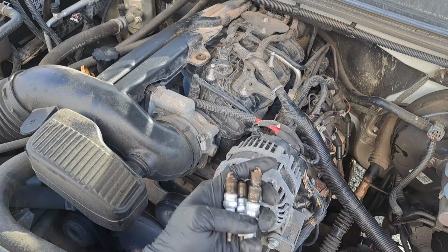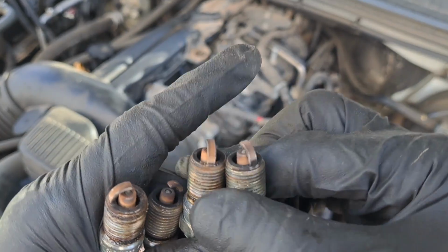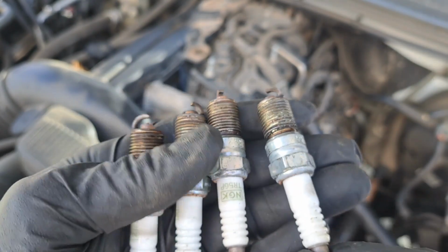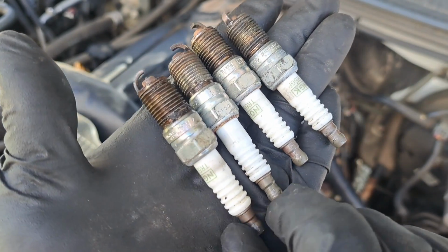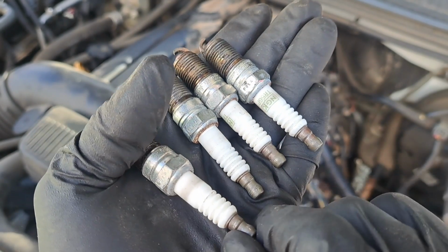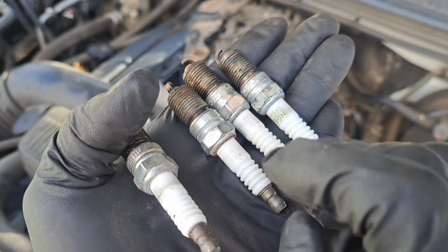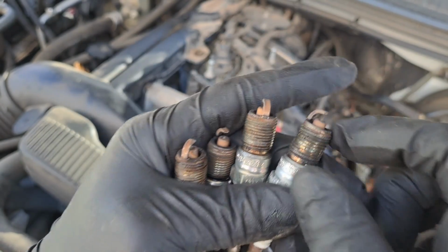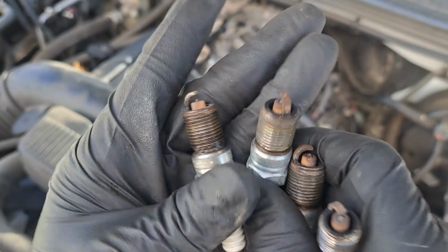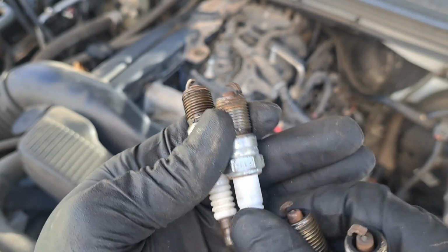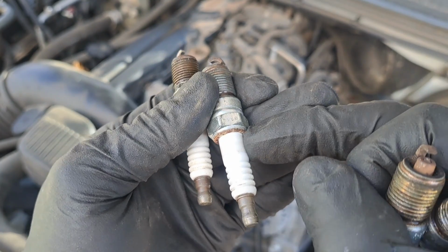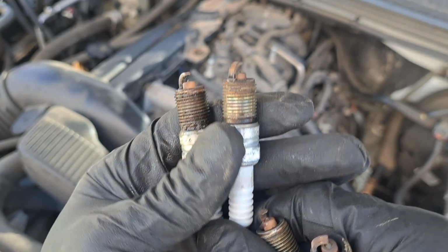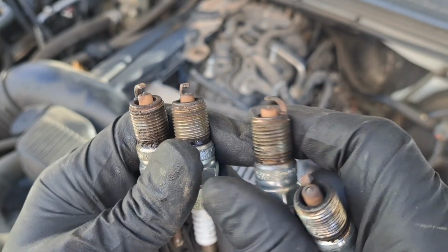So I got the bank 2 plugs replaced. They were just as bad. Let me see if we can get these up. They were just as bad, but they didn't have what I assume to be potential arcing conditions in the porcelain here. So the body is fine. The plugs are just naturally worn. They're not aged, but normally I look for that flash bang on the porcelain, and this doesn't display that, likely because these are a better quality plug, NGK.